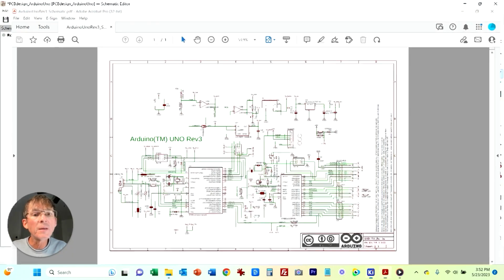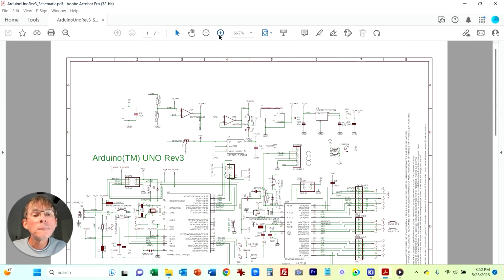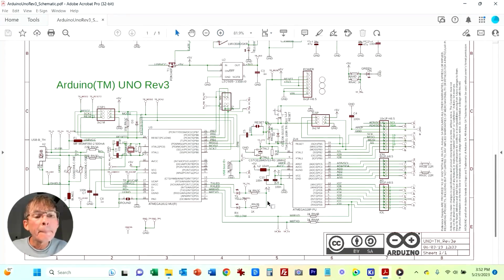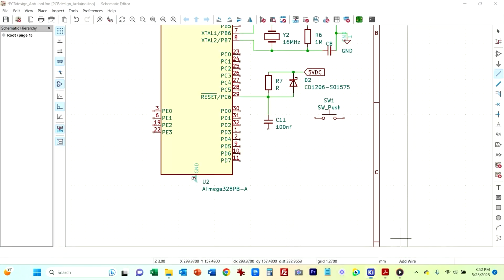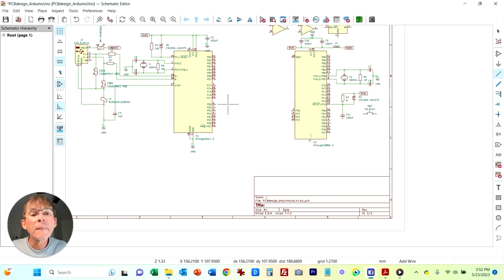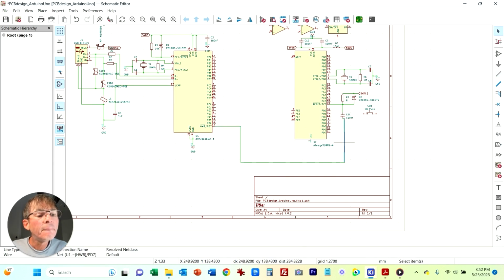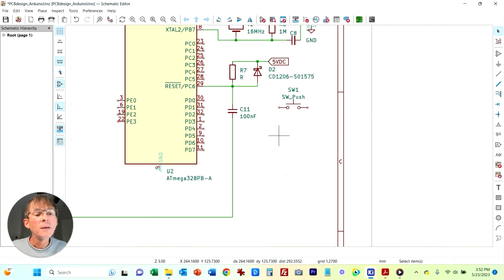Let's go ahead and connect that up, and that's going to go over to the first microcontroller. So this capacitor here, it's going to go to PD7, okay? And PD7 is right here. Okay, there we go. Next, we need to tie this in. And then this side will just go to ground.